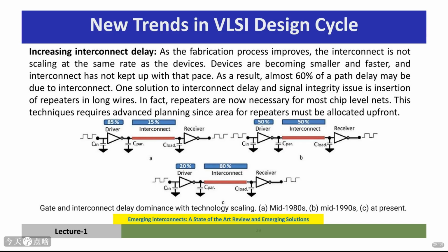One solution? Repeater insertion, adding small amplifiers along long wires to boost the signal and reduce delay. This requires careful planning up front. It's a fundamental shift in how we think about chip performance.